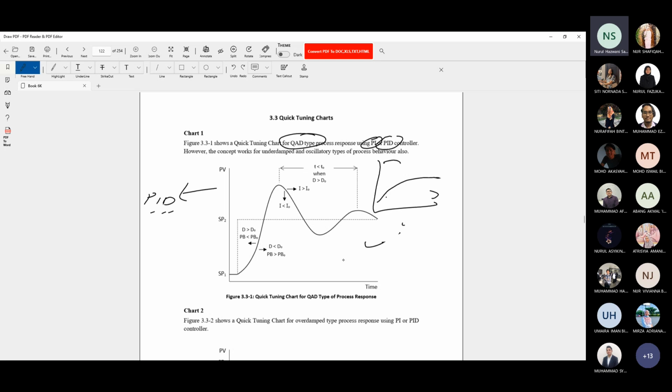And then now we do set point changes, so you need to change the value of P, I and D. Okay, we can see from this graph, the solid black graph is the original graph, with the original values of P, I and D. So if you want to tune the values of P, I and D,